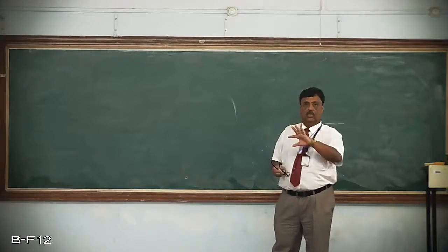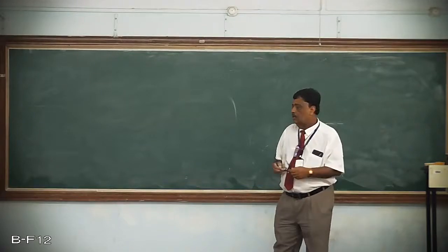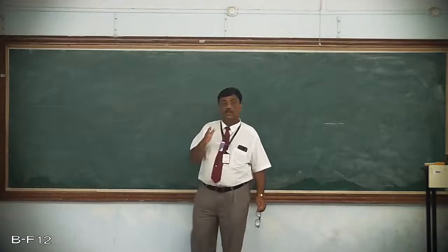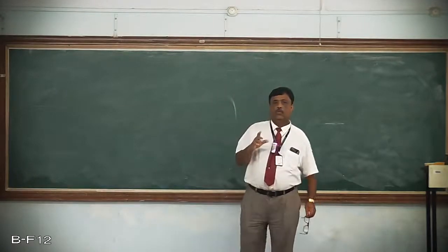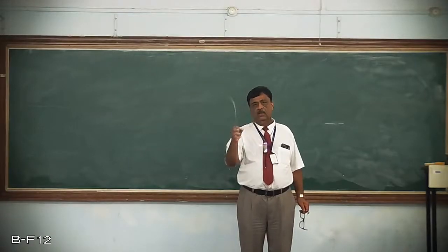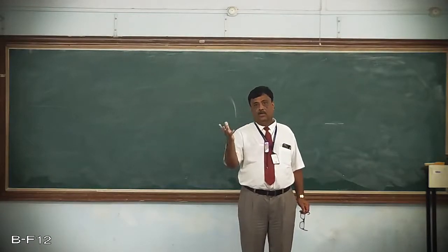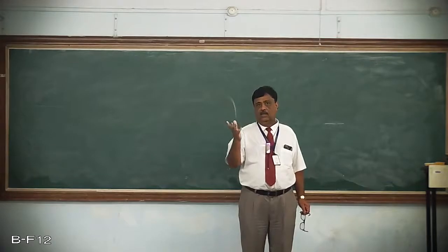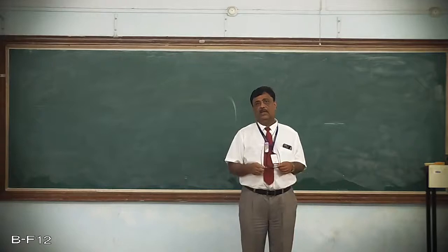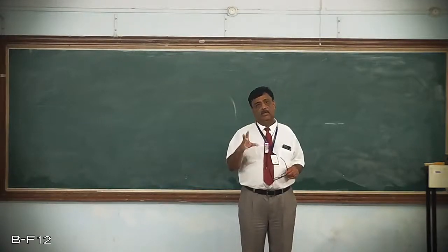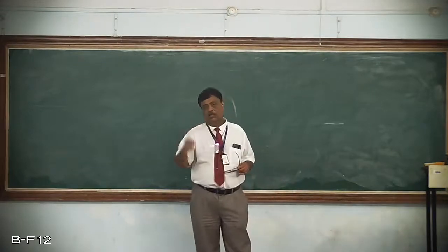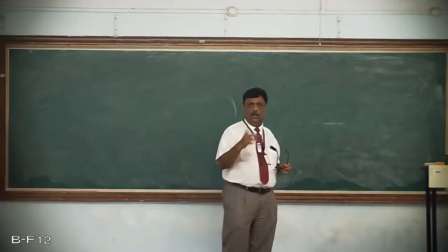The moment the order of the polynomial increases, the accuracy of the results also increases. So if we can develop elements wherein the shape functions contain higher orders like zeta square and eta square, then our results become more accurate and you can map even curved boundaries, because the square terms are higher order terms.